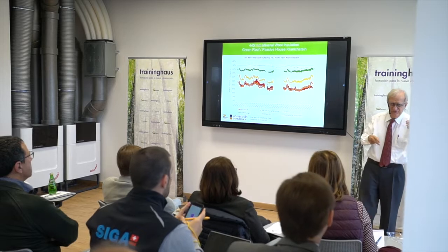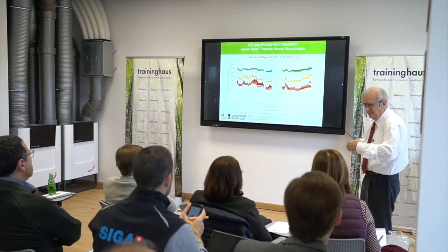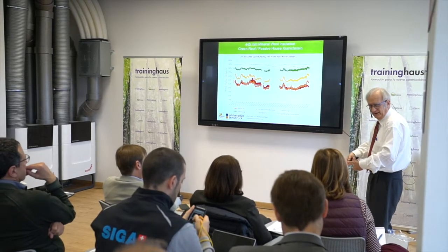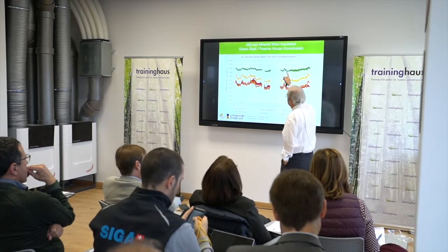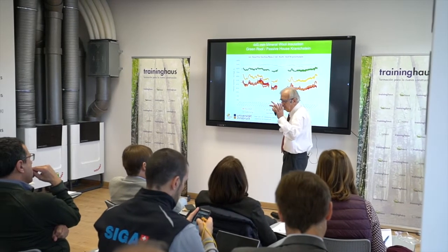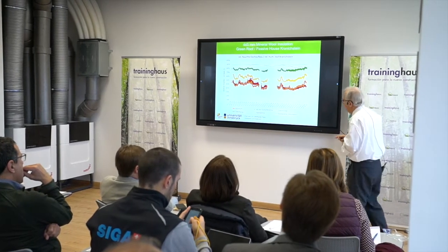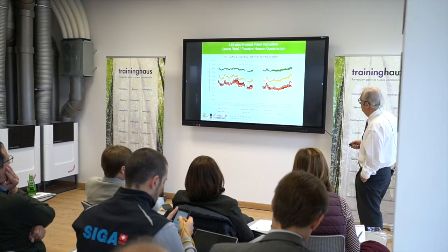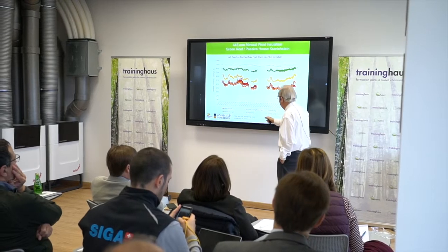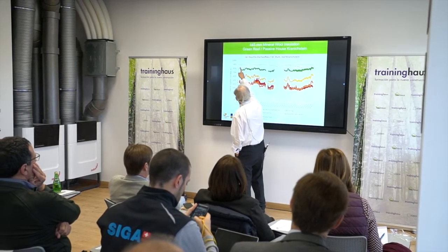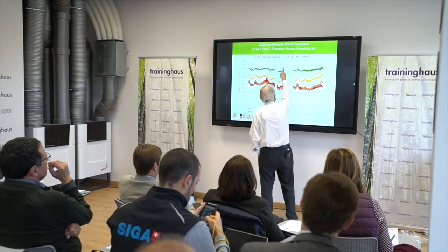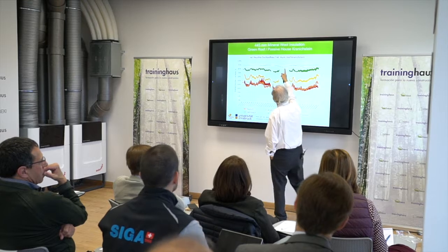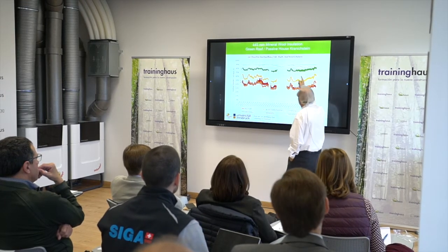Because just the temperature drops, and with the drop of the temperature, the capacity of the air to hold the water is less, so the relative humidity will be higher. And of course, also on the outside, we have outside air with a humidity of around 90 to 95%. So that is normal. What shouldn't happen, it should not go up to levels above these 90%. And that's what we see here. So we have the measurement on the internal side of the external sheeting, and that's around some 90% here, and that's the corresponding simulation.